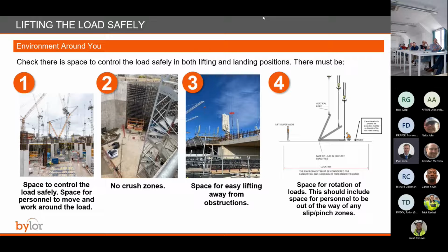And the simple one, space for rotating loads. This is actually one people just don't really think about. You're lifting and tilting a load. People often say, well, I won't walk underneath the bit where it can drop back down and squash me. Yeah, but what about where it slides? Now, if the load's done properly, it'll have chocks, it'll have blocks, it'll be lifted in such a way it can't happen. But you never put yourself in that situation. You always make sure you're out of it. You always plan for the worst, and then we can only have a good outcome.